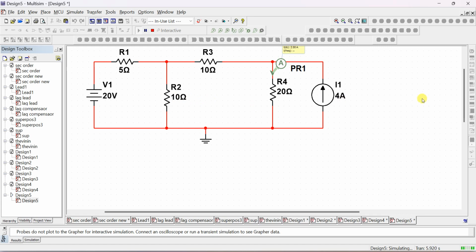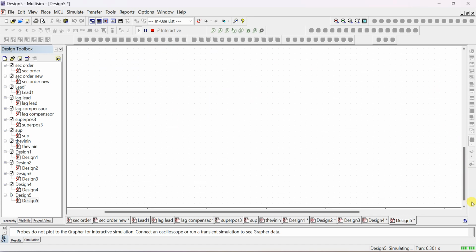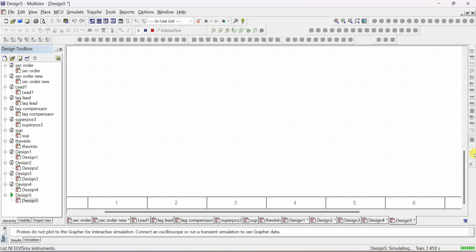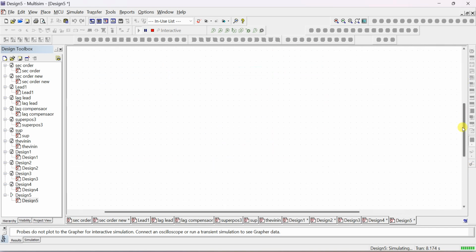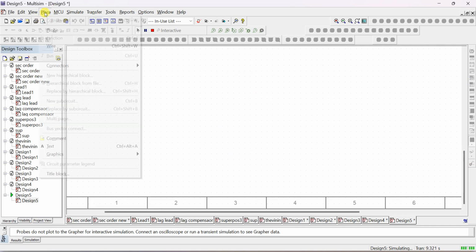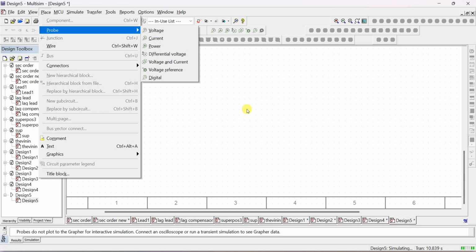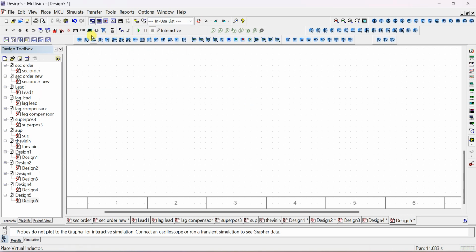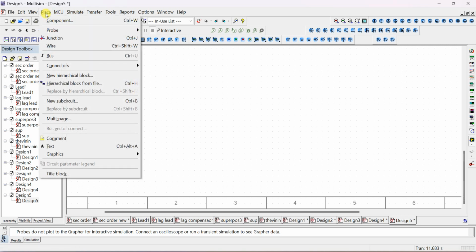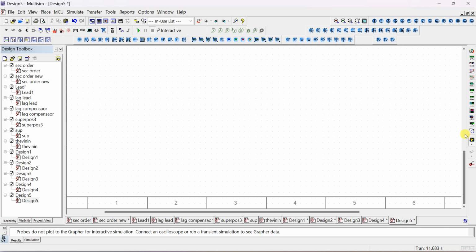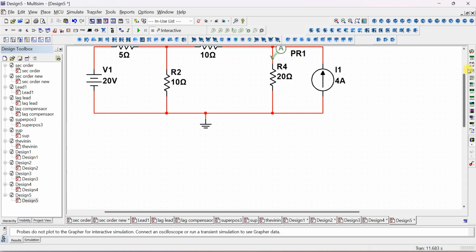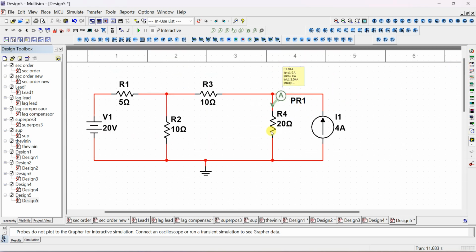So what does Thevenin's theorem state? Any complex circuit, for example, this is a complex circuit, right? This can be replaced by one voltage source. So I don't know what is the value of voltage and what is the value of resistance. I will just write here. Later I will do that part. So first I will find out the voltage source. You have to find out the open circuit voltage across this.